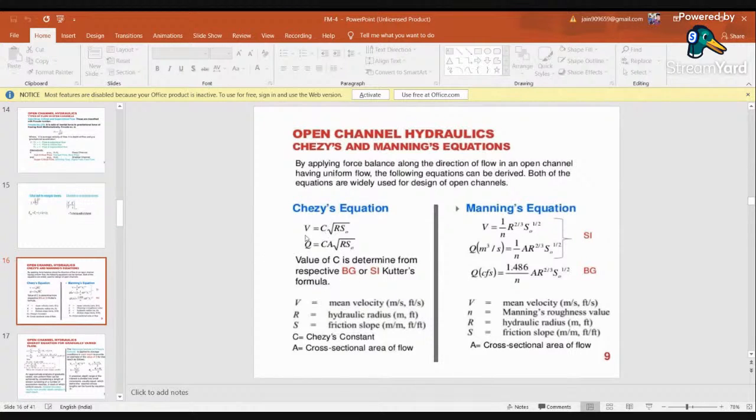When we replace this in the continuity equation, that is Q is equal to area into velocity, we get the final discharge equation as Q is equal to CA square root of R into S0. Here C is Chezy's constant, S is the slope, A is the cross-sectional area, R is the hydraulic radius, and V is the mean velocity.